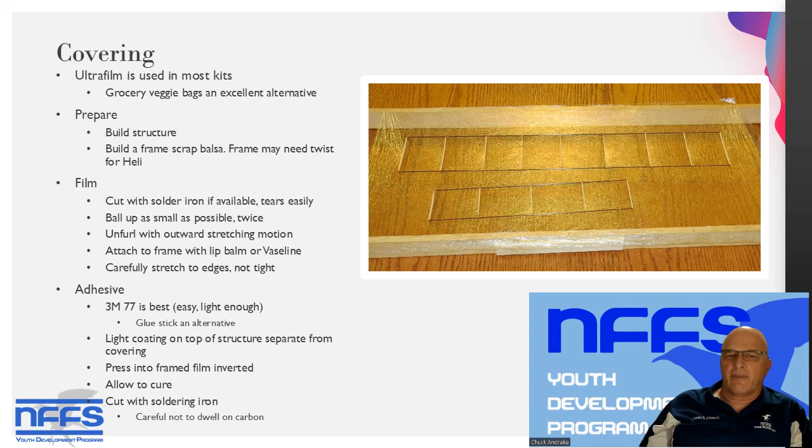We like to use 3M77. You spray a light coating onto the frame of your rotor, not the frame that's supporting the covering. And then gently place the rotor onto your stretched out covering, knowing that it'll immediately stick. So make sure it's in the right place before it touches. Glue stick is an alternative, although it doesn't work great with the plastic coverings. It works better with a tissue covering. 3M77 spray glue is available at Home Depot or Lowe's or even Walmart.